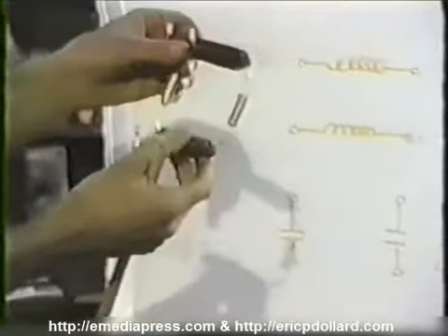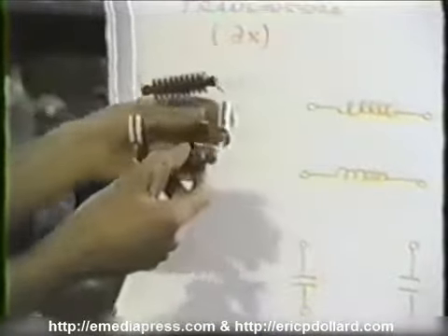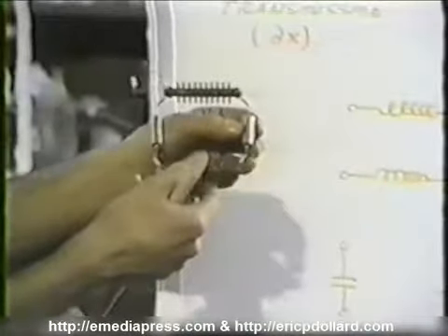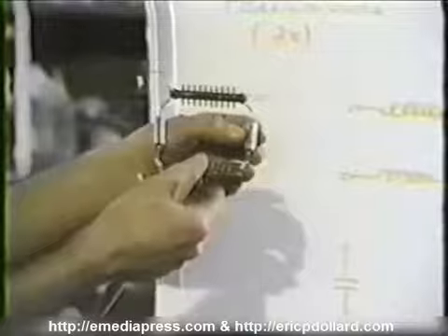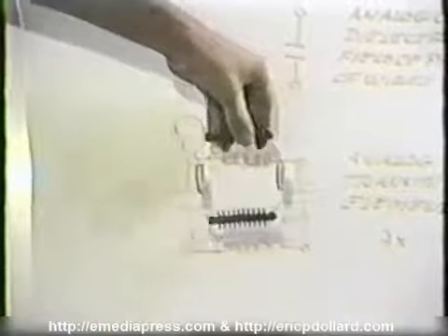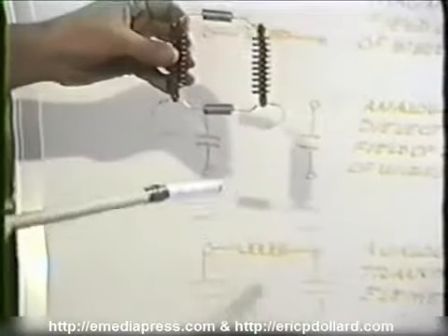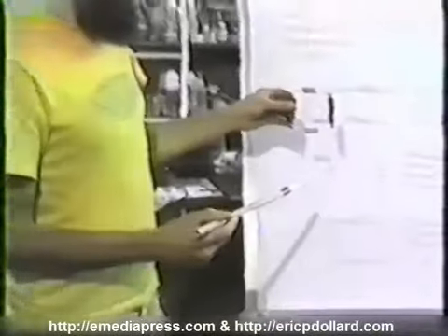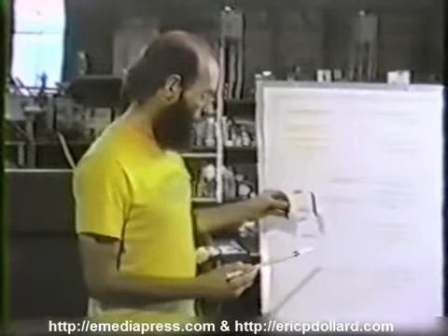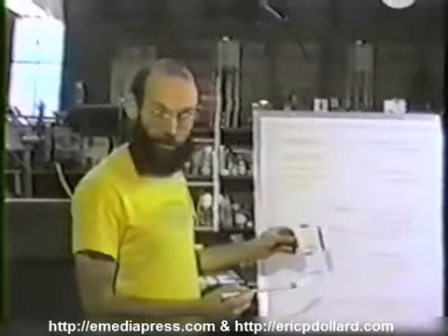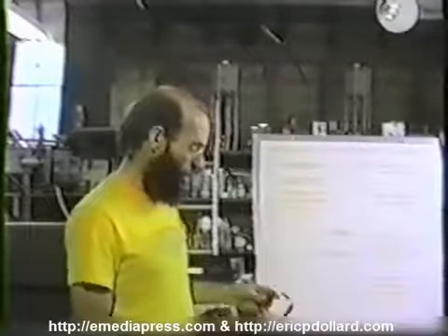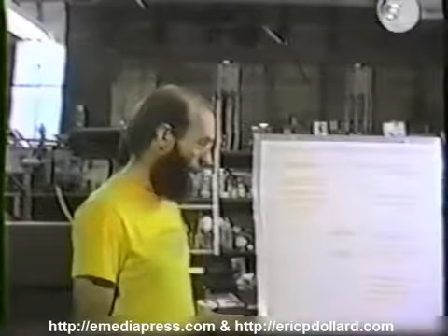And we have some radio frequency inductance coils of 10 millihenries, and we have some high Q pulse capacitors of 0.047 microfarads. This constitutes one element of transmission. And of course we can propagate either longitudinally or transversely, and we're going to stack these elements up to symbolize and synthesize these 2 forms of waves, and then we're going to get in there with some rather unique detectors and some conventional detectors, and even use our fingers and determine exactly what's going on with these things and see how this correlates with our previous measurements of actual transmission structures and not their analogs.